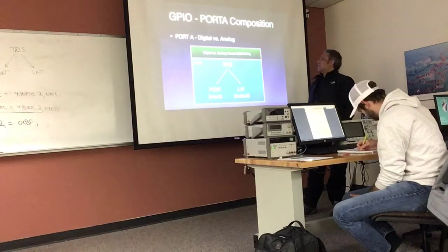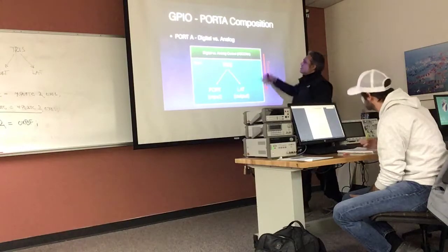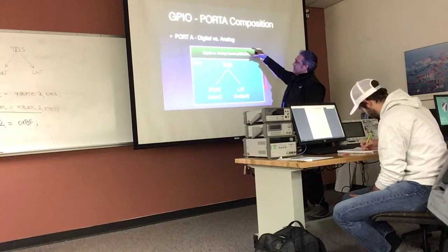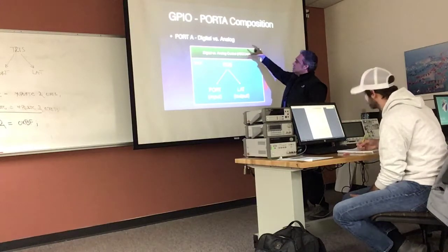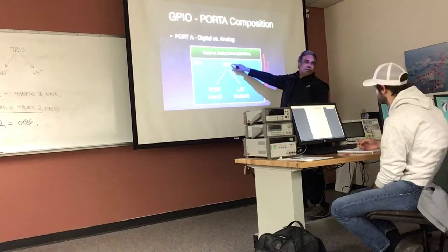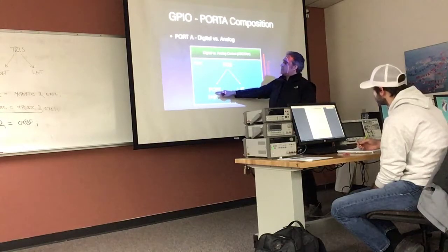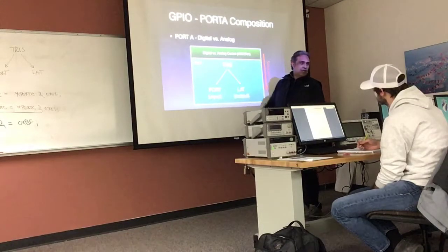Okay? So what this means is that you got to follow the sequence, right? You got to have the analog control taken care of first so that the tri-state makes sense. And you cannot mess with the port unless the tri-state has been set up properly. See that?